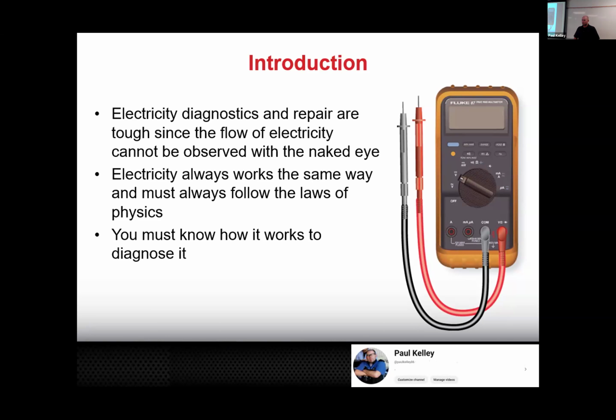The other thing is, when you disconnect and visually inspect, you're disturbing the harness. If it's an intermittent problem that's hard to duplicate, and you get lucky and it's doing it right now, your best bet is really to do the measurement, to observe, to verify, to measure the fault.